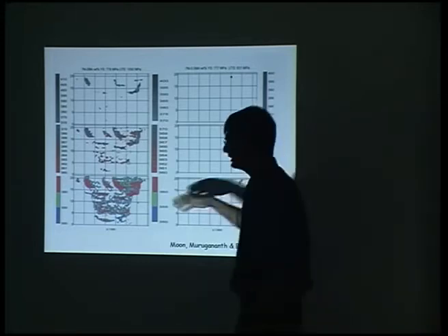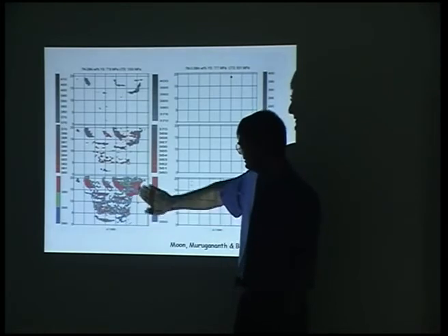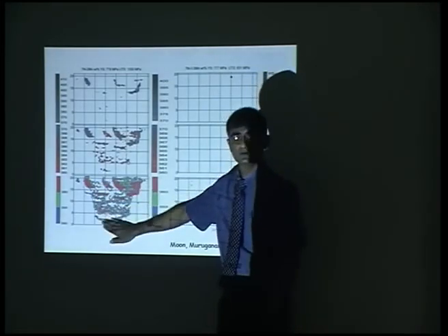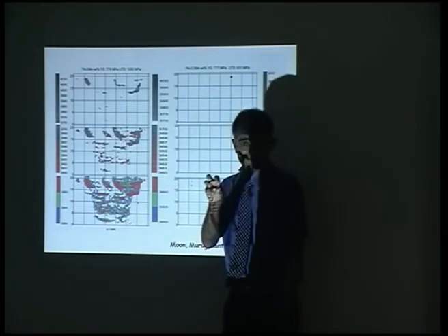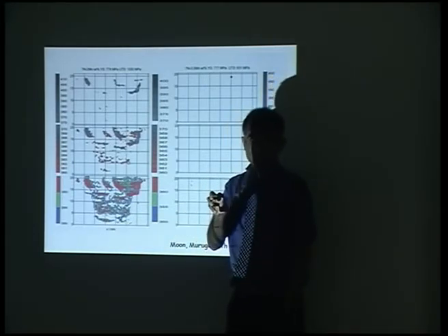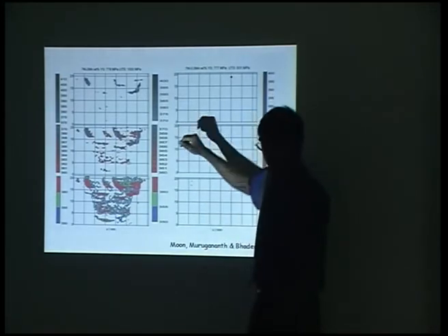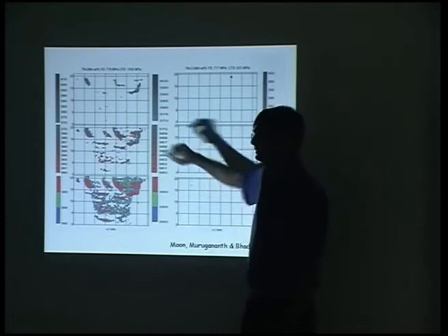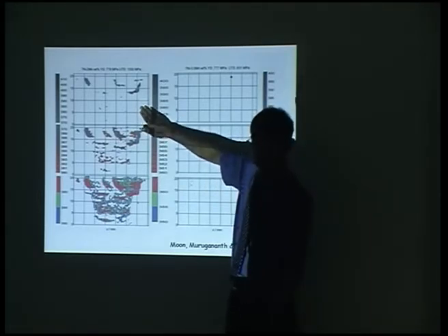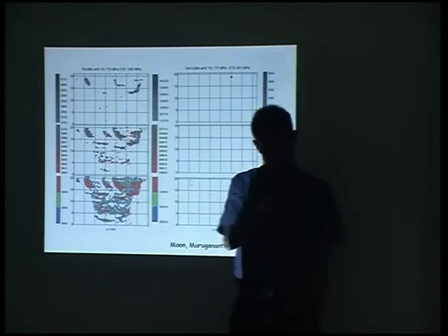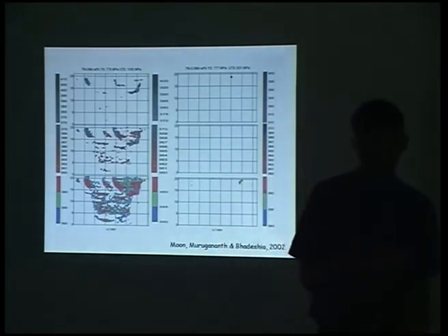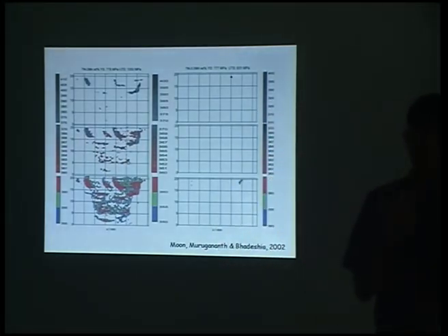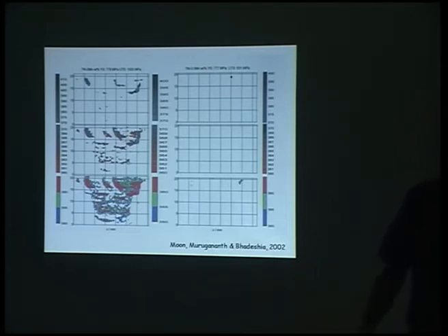And what happens when you have a high manganese and high nickel concentration is that you get these very hard spots inside the weld, because the hardenability in those regions is very high because of chemical segregation. When I reduce the manganese concentration and have a high nickel concentration, I get that. And we can show using thermodynamics that the segregation levels here are much less than over here. So that's a physical insight which comes from the neural network modeling. And it's simply that, as human beings, when we see that nickel has increased the toughness in a particular alloy, we assume that it will do it for everything else.